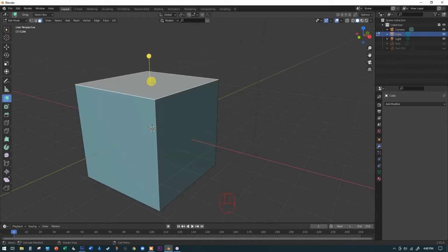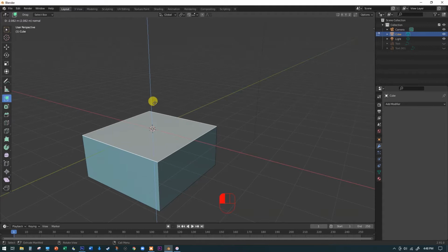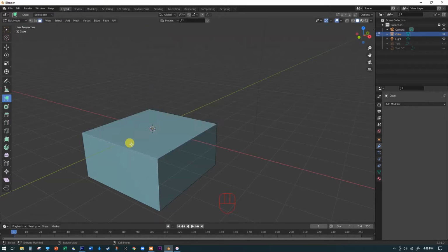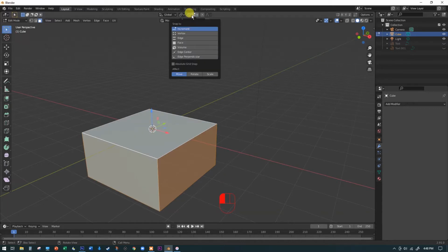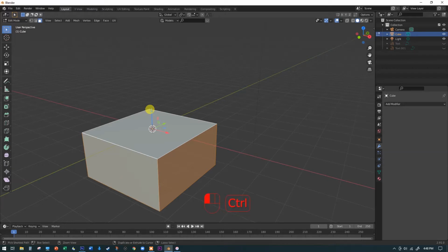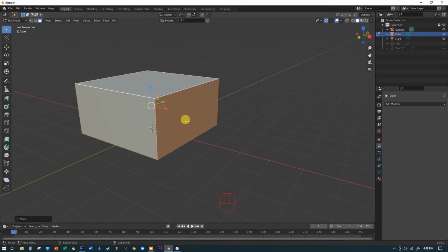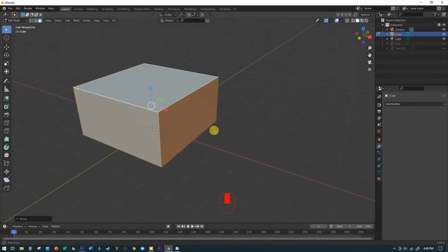I'm going to come over here and grab this top face and just push it down a little bit. That looks fine. That'll work. And now I've got a box that will fit the scene. I'm actually going to hit the A key and hold the snapping down. I've just got the regular increment snapping down, and I'm going to hold down my control or command button here, grab the blue arrow on my move gizmo, and I'm just going to pull this up 2 snaps there. Snap, snap, and that should pull it right up onto the floor plane. You don't have to do that, but it's a tidy thing to do.